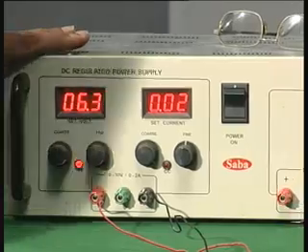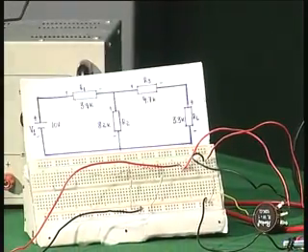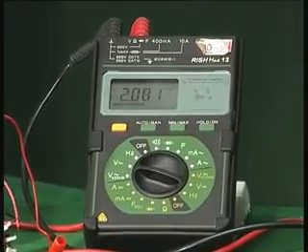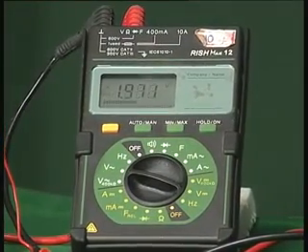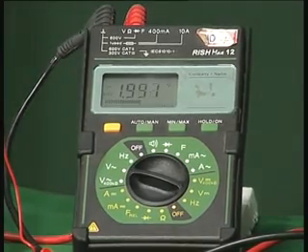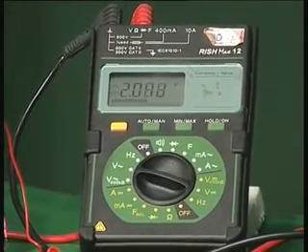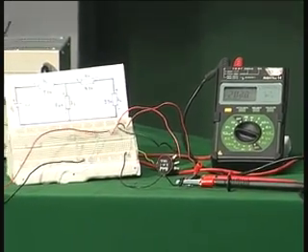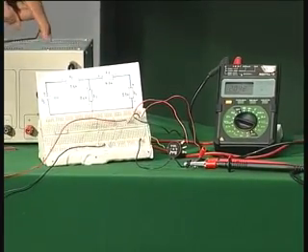Yes. So now we will have to measure what is the voltage. You can see the voltage is around 2 volts. We calculated 2.1 volts in the actual situation, and therefore it comes very close to that. And I already explained to you whatever difference is because these resistors that we have used are not exactly equivalent to whatever the color code says.